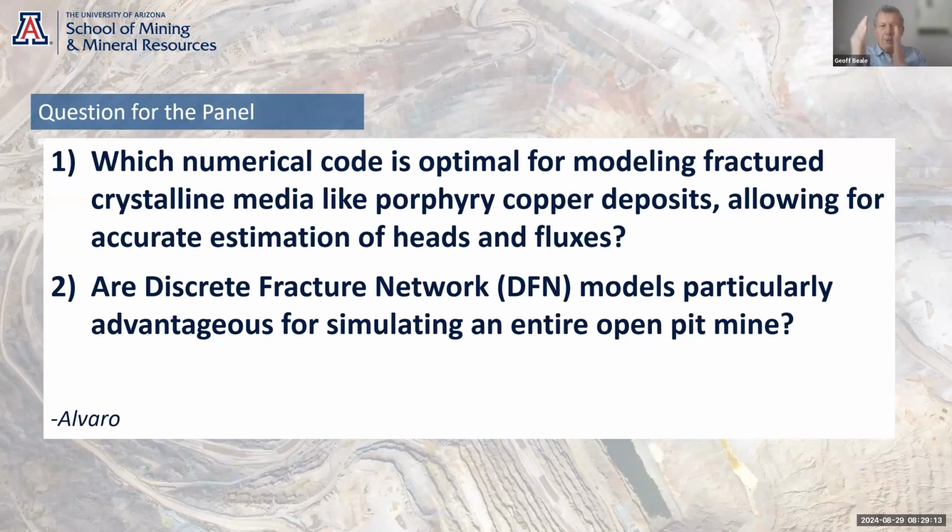The error on the assumptions is 100 times. So what makes a good model is the geological base, the number of water level measurements you have, the calibration to transient conditions, and the assumptions that you make.